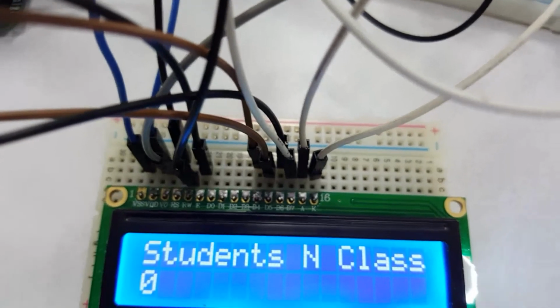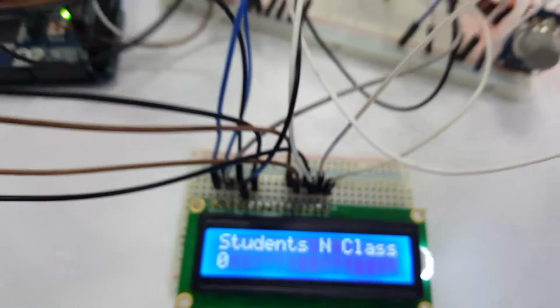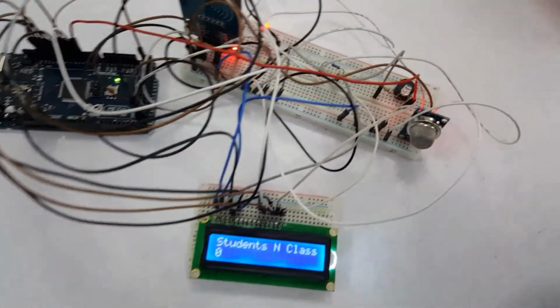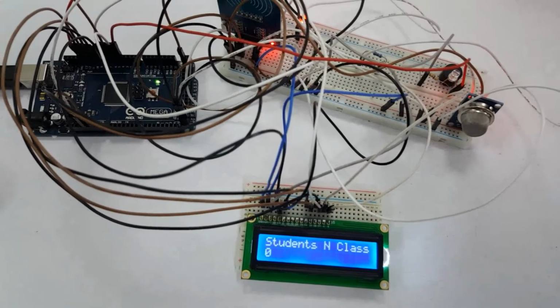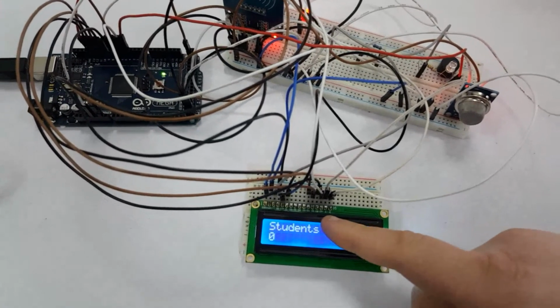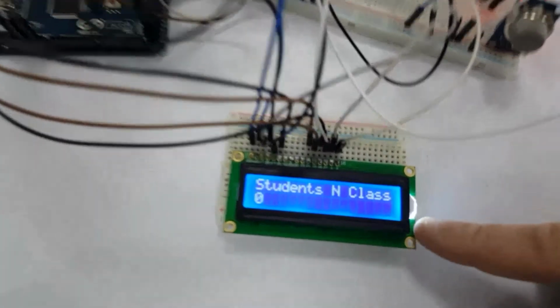And we have 8 pins for the data. But we only use 4 pins out of these 8 data pins because we use the mode that only uses these 4 pins. There are 2 modes that use either the low pins or the high pins. We also have 2 unnecessary pins here that connect to light the LED over here, the ground and the voltage.